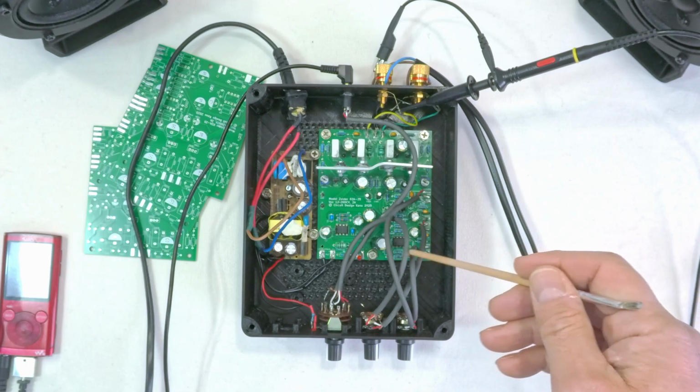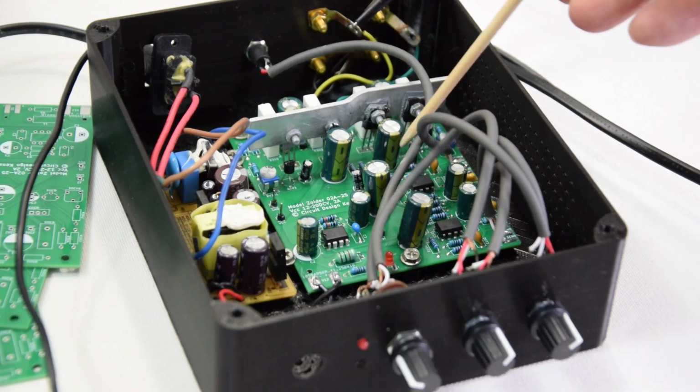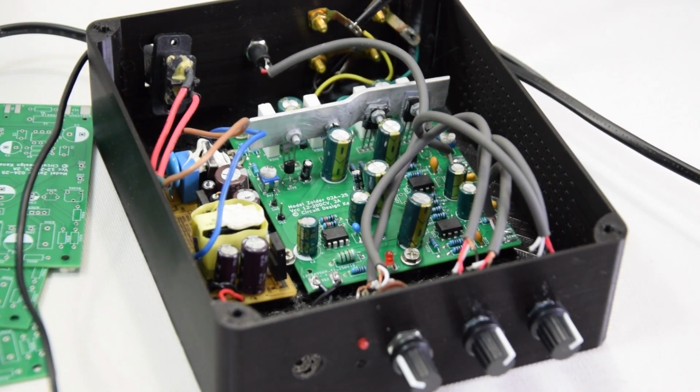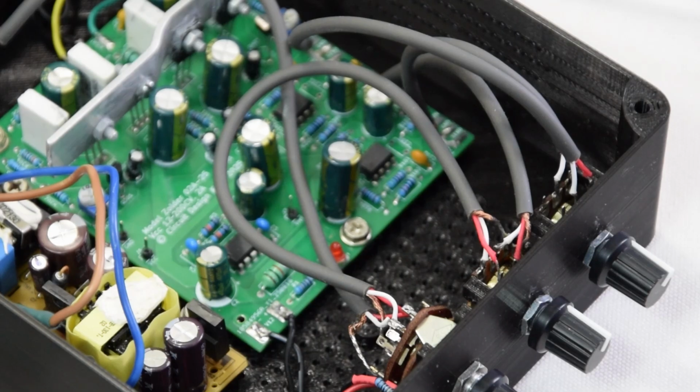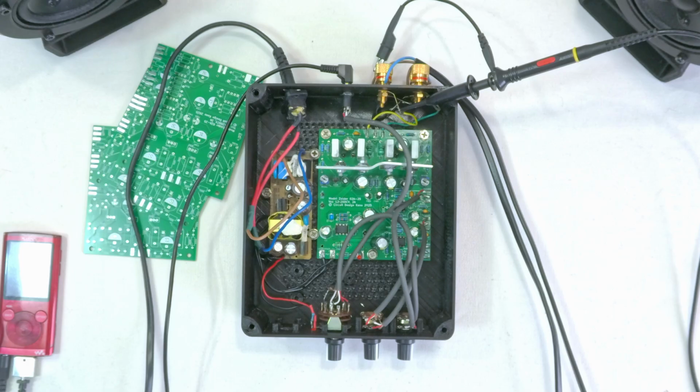For the wiring, I used all shielded cables. This is the best way to protect your low-level signals from external noise. I've been extra careful to connect the ground wire or the shielding wire only to one side. It is strongly recommended to avoid ground loops, as this can lead to noise in your audio output.